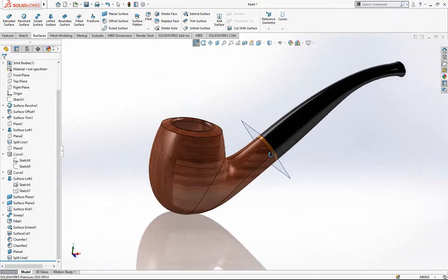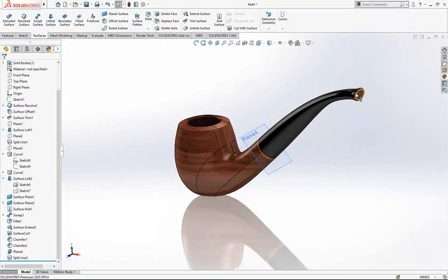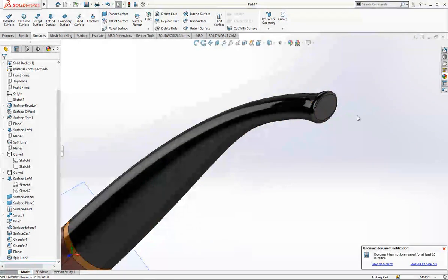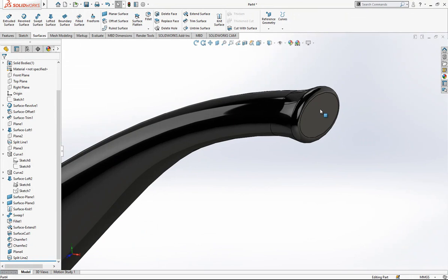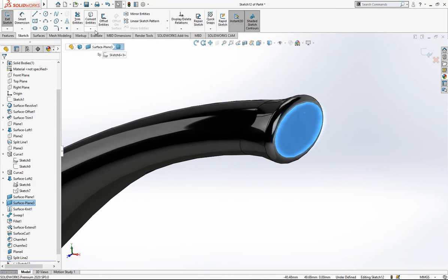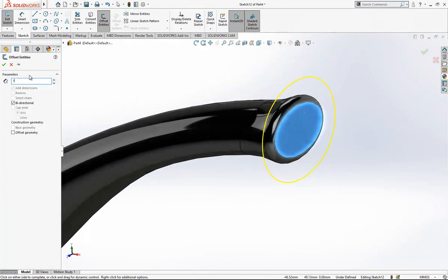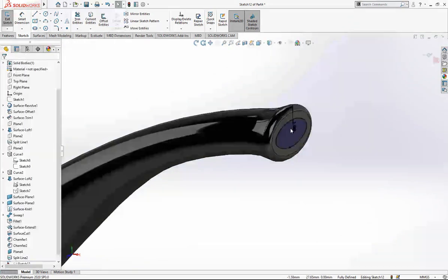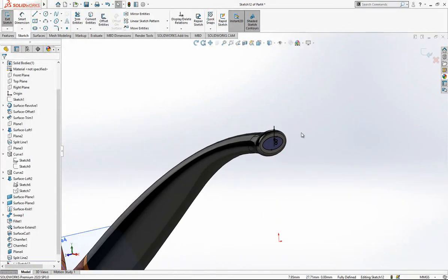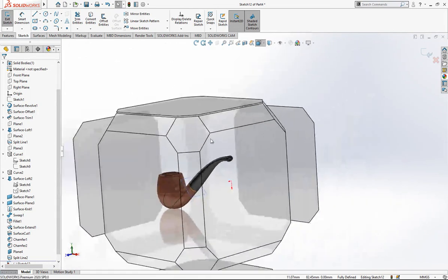And just one thing is missing. We don't have a hole inside of the tunnel. How do you call it? I don't know. I will make an offset here. Let's make inwards 1. And I will make a sweep to cut inwards.